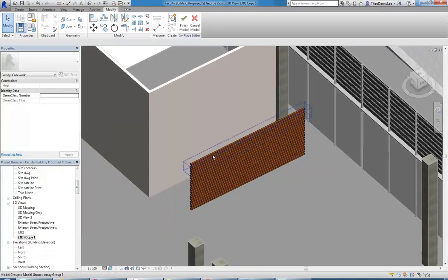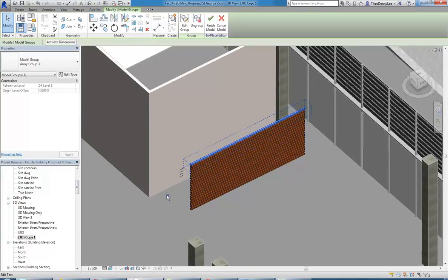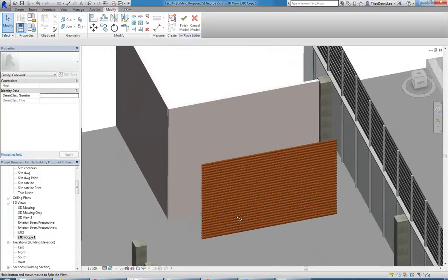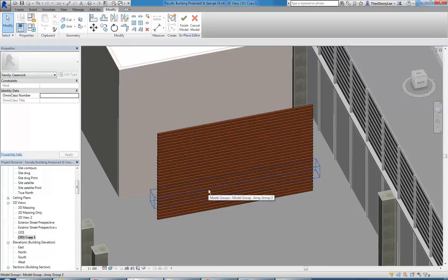Now you might think that's basically the same as what I had with the extrusion that I modelled, but the advantage in terms of your file size is that Revit only needs to store that object once. And then each time it's copied, it just needs to store the new insertion point for each copy. So in your project file, it's just got the original family defined once. Whereas if you do it with an extrusion and then copy the extrusion multiple times, it's got to store all of the geometry all of those times that it's copied, which will make the file size much bigger.